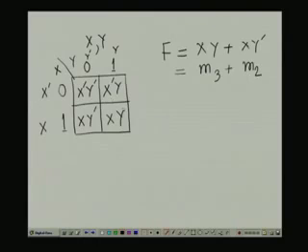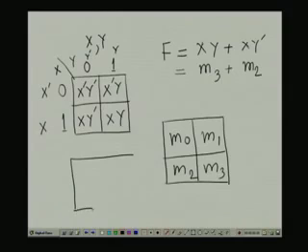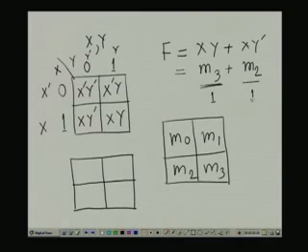Now, how will this K map, Karnaugh map, be then? Say actually this is the position of M0, this is the position of M1, this is the position of M2, this is the position of M3. So here we have seen that the product term, that means the minterm for these will be 1 and the function here will be 1.